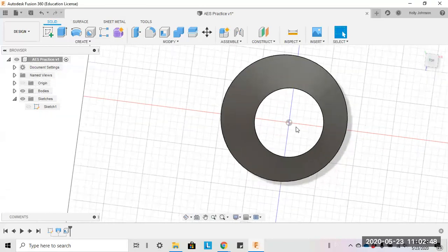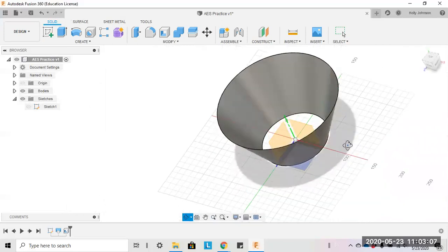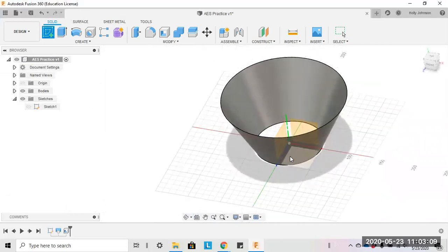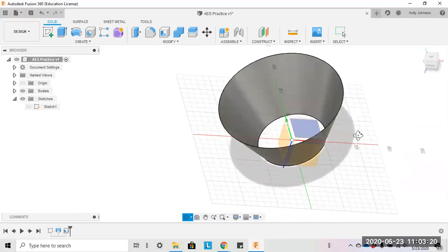If you would like to do something in addition to this, I was thinking, let's say I have this speaker cone, and I would like to create the bolt holes on the outside of the top. So you can go ahead and create another sketch. Initially the sketches only gave you the option to sketch off of these three axes, right? Of course, if you defined your own axes somewhere, or if you move those axes, you can base it off of that position or offset from those locations.